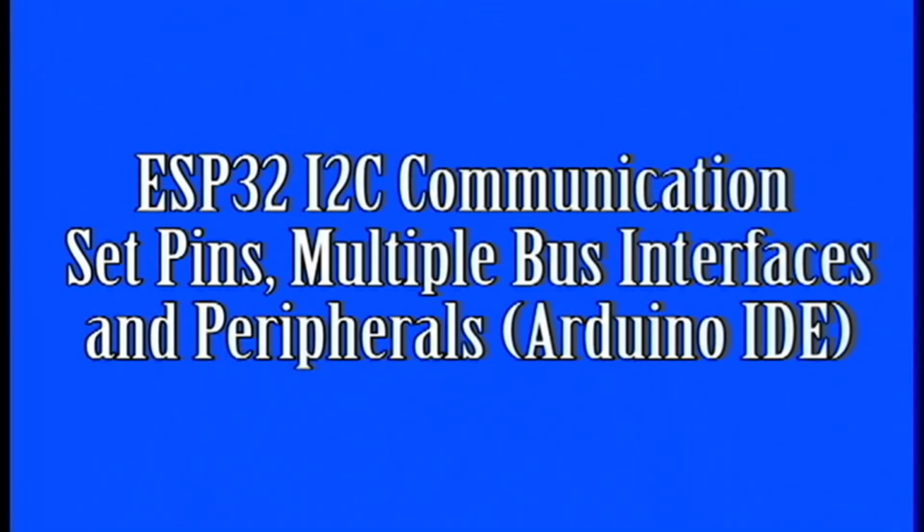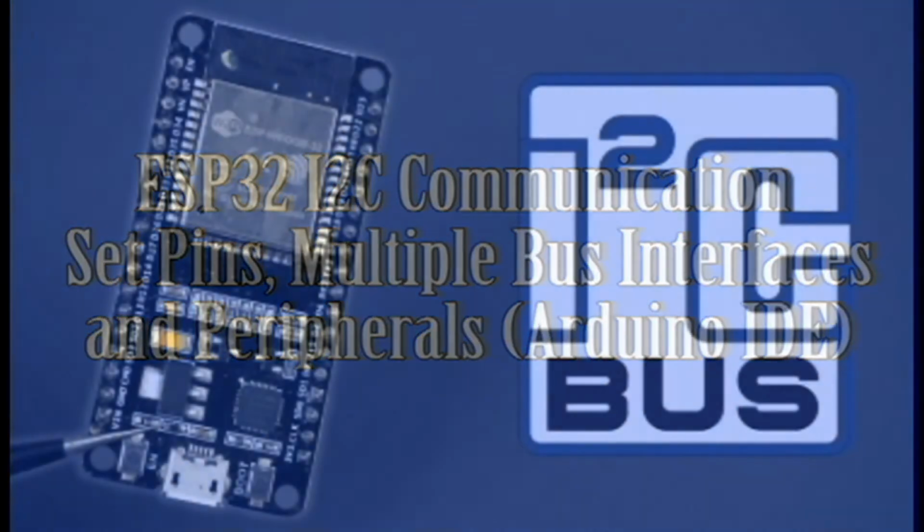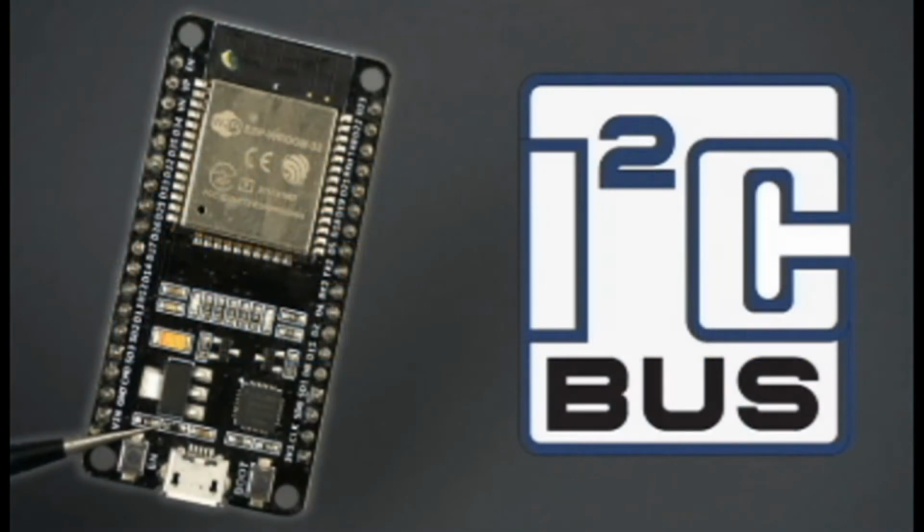ESP32 I2C Communication, set pins, multiple bus interfaces and peripherals, Arduino IDE. The ESP32 has 2 I2C bus interfaces that can serve as an I2C master or slave. We'll look at the I2C communication protocol with the ESP32 using Arduino IDE, how to choose I2C pins, connect multiple I2C devices to the same bus, and use the 2 I2C bus interfaces.